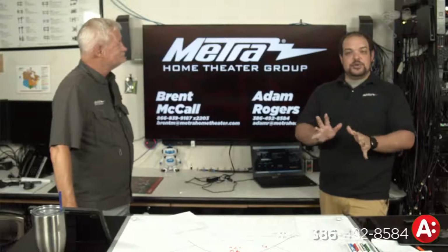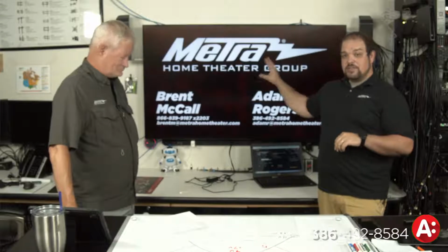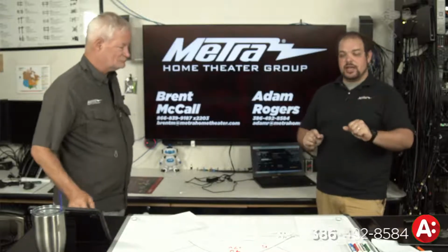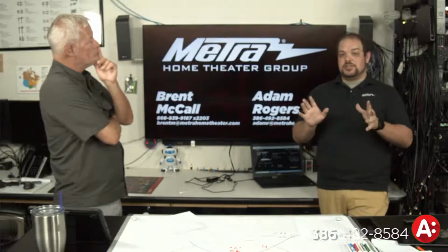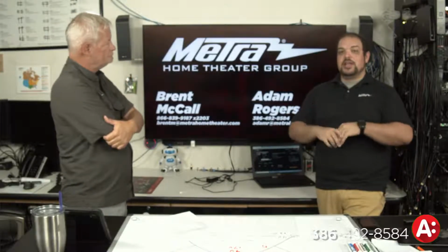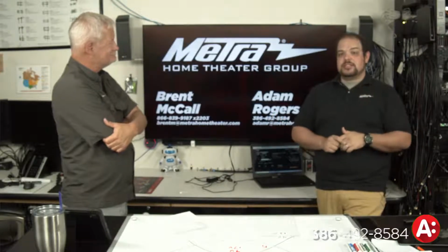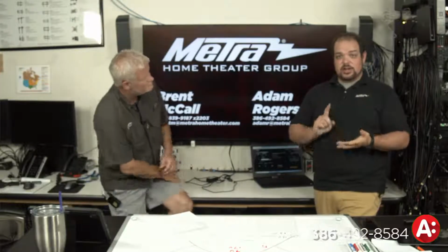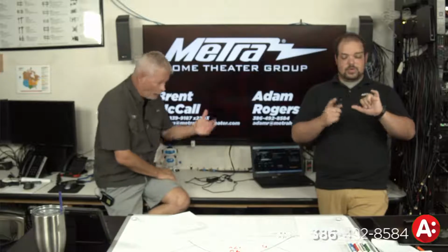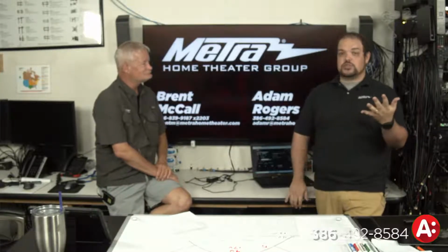So technically, you could take a device like that and transmit only the data connection or only the video information. Let's use an HDMI extender as an example. You could send just the video information down the fiber, gain that increase in bandwidth, and use the category wire instead to handle things like EDID, eARC and ARC, CEC, and power, of course. At that point it's very easy to do, because all the other stuff is super, super low bandwidth. And this is not a new concept.